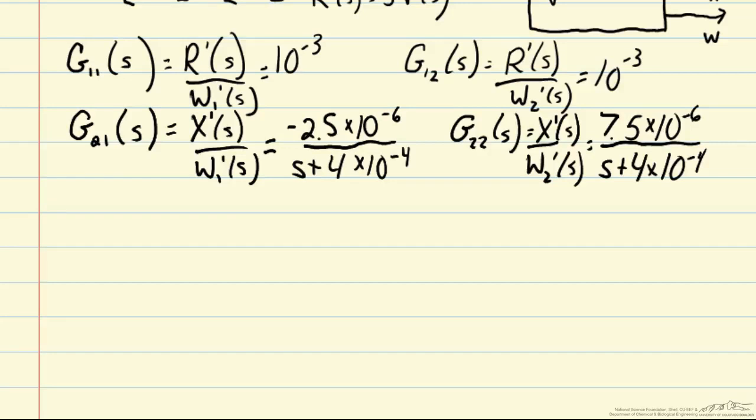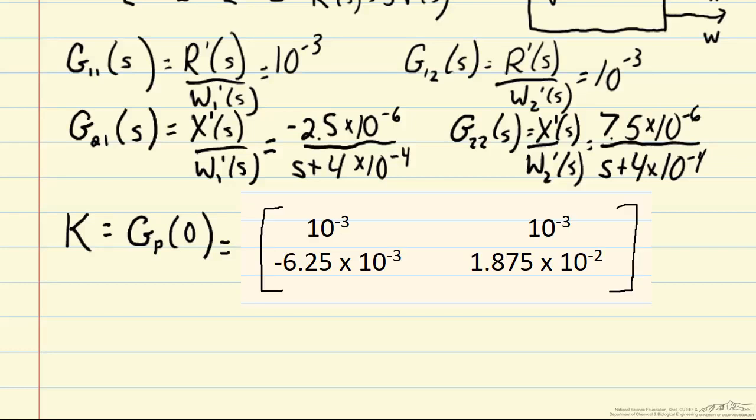In this multivariable context, we can also express the overall steady state gain of our system. We can calculate this as GP of 0. Really, we're just going to write out the gains associated with each term. We can also think about calculating this steady state gain using the final value theorem, which we saw in an earlier screencast. In that case, we had s, G of 0, and then if we evaluate that for a step input, we get a 1 over s term. And so those s terms cancel, and then we're just left with G of 0 from the final value theorem.